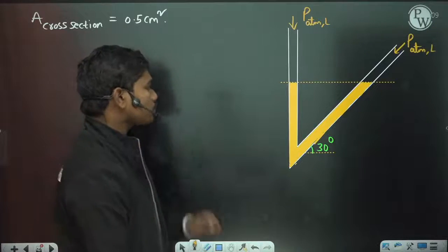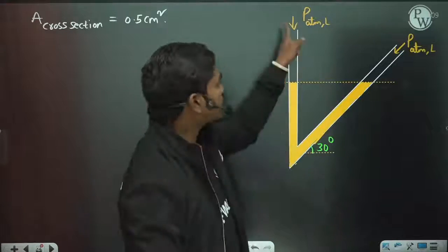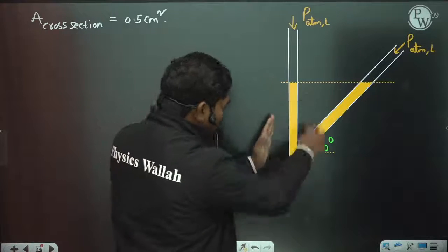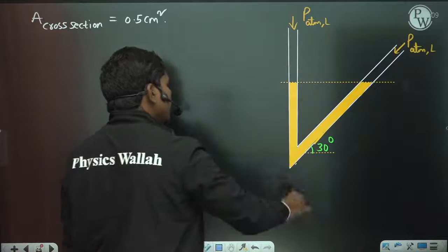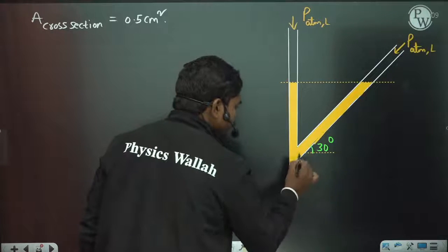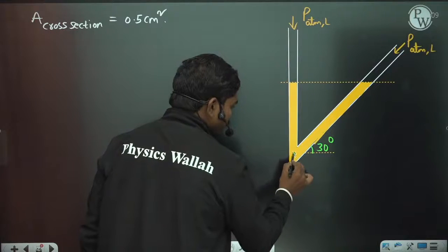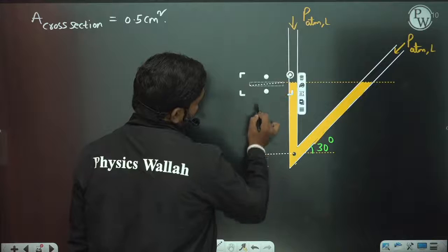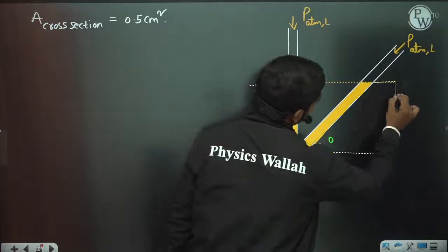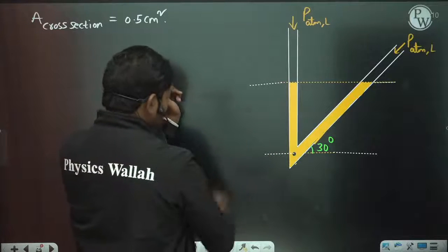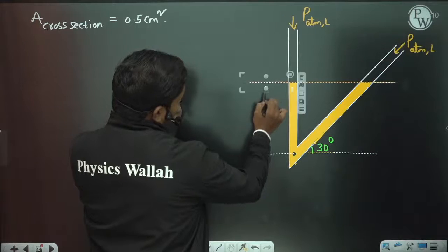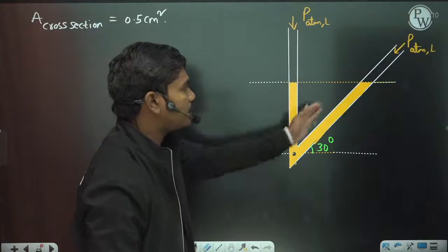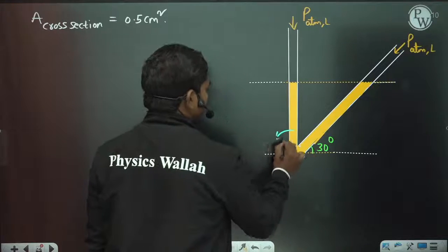Thank you. Now see here, normally when you don't connect any pressures at this location and this location, if both are open to atmosphere, then this manometric fluid which is poured inside will come to such a level that the pressure due to this fluid column will be the same as the pressure due to this fluid column, because for pressures to be the same, the vertical separations should be the same. So the manometric fluid levels get settled like this. This is a fluid of density rho m.